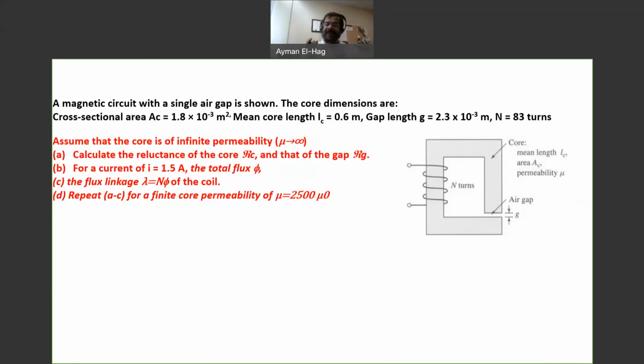In the magnetic circuit, we have the MMF, which is equivalent to the EMF, the reluctance, which is equivalent to the resistance, and the flux, which is equivalent to the current. So when you look at such a magnetic circuit, the first and most important task, before even reading the question, is trying to find the equivalent electric circuit.